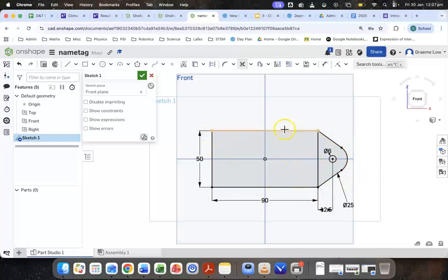Like I said, I wanted to make some of these corners rounded as well though, because 90-degree corners don't play nicely with a 3D printer. So I might leave these ones as they are, that's alright. But I want to round these ones off rather than having a sharp 90-degree turn there. So if I want to round corners, the tool we use is called Sketch Fillet. It's this one here where my mouse is. To use the Sketch Fillet, press on it and click on the two sides. And then from there, you can drag this in and out, or you just click and pick a number.